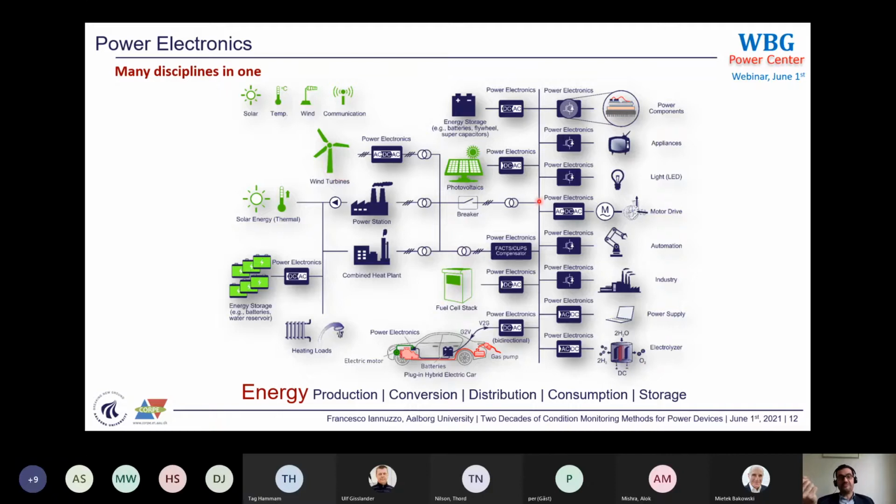On the other side, you have very constant frequency and voltage demands, for example in the case of a national grid. So what you need to do in between is, number one, to provide storage, which is very important because you have to accumulate energy when you do not produce it, but still utilize it, and then the opposite. The other thing you need is to equalize, to make as uniform as possible the energy parameters, which are not constant. Wind speed is changing, solar irradiance is changing, but you need to feed constant frequency and voltage to the grid.